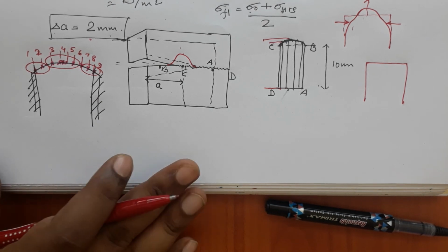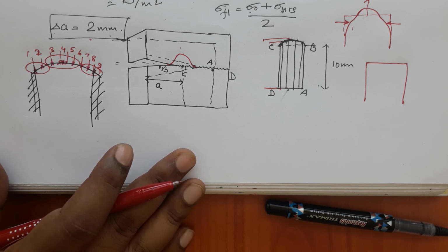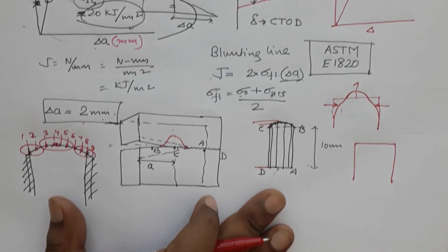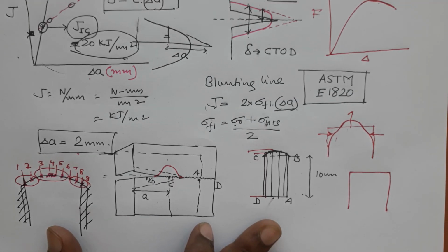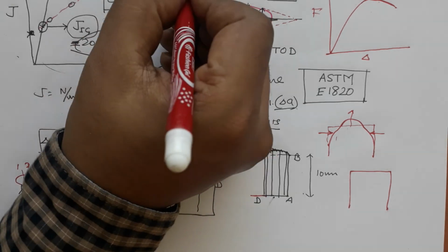So, we will stop here in this lecture, and in this lecture we tried to understand how we calculate fracture toughness for a plastic material, predominantly plastic material, unlike what we learned for Griffith's criteria, which was completely brittle, and also Irwin's stress intensity factor, which worked for moderately plastic material as long as the plastic zone is 50 times smaller than the smallest dimension of the specimen. We were good to apply the concept of K1C.